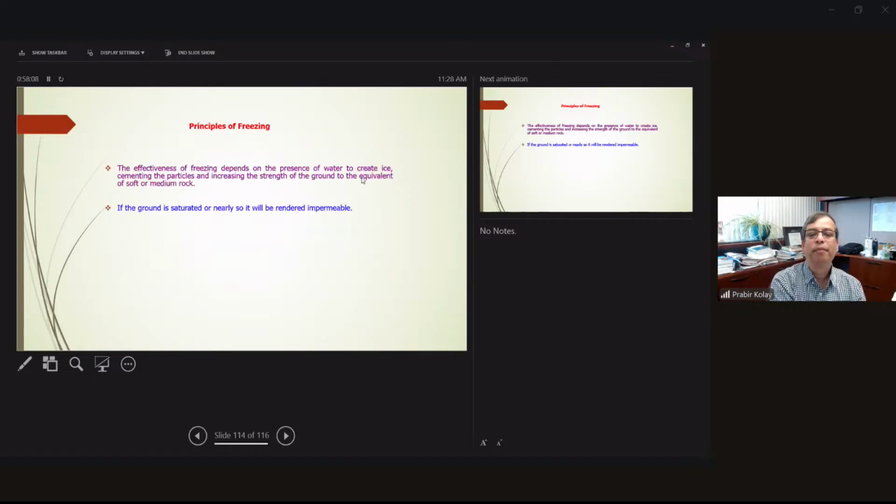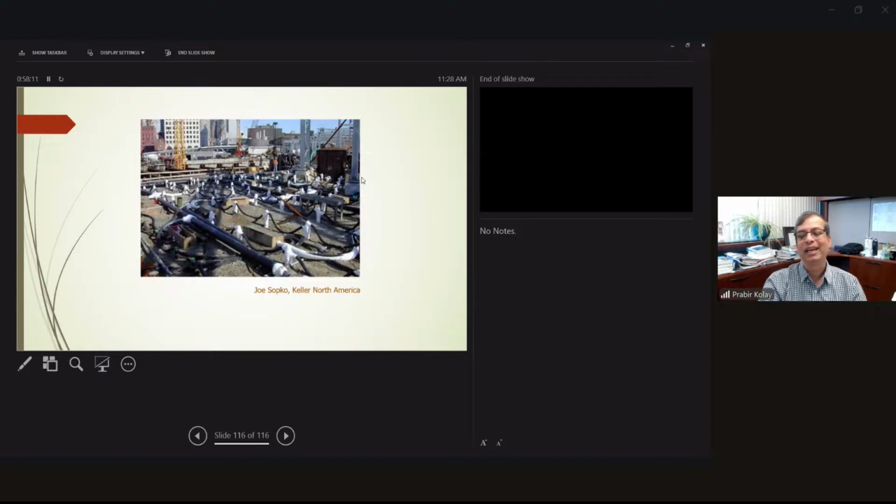I think principal freezing, I'm not going to go into detail over here. So basically, this is another freezing technique. As I mentioned, Joe Sopko is the director for the ground freezing company, and we developed that ASCE Geotech tool. There is a lot of information there, and you see the different pipelines over here. Basically, the header and riser, the same thing we mentioned with the dewatering technique. The only thing is, in the pipeline here, we need to supply either liquid nitrogen or calcium chloride. That's all.